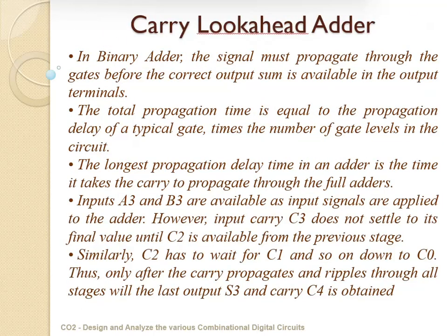And next we'll move on to carry lookahead adder. In the binary adder, the signal must propagate through the gates before the correct output sum is available at the output terminals. The total propagation time is equal to the propagation delay of a typical gate times the number of gate levels in the circuit. The longest propagation delay in an adder is the time it takes the carry to propagate through the full adders. We are providing the inputs A3 and B3 at the same time.